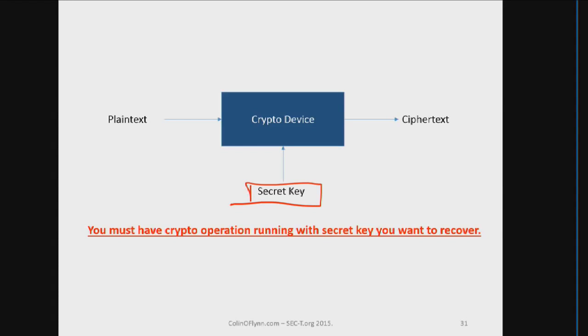Why I say that is that, if you have a hard drive on a table that's been encrypted, side channel analysis is no good for you. It's not actively doing anything, encrypting or decrypting the data. If it's just sitting there, the key's not loaded in the engine, so you can't use it. If it was actively being in use by the user, you then could use side channel analysis on the device.